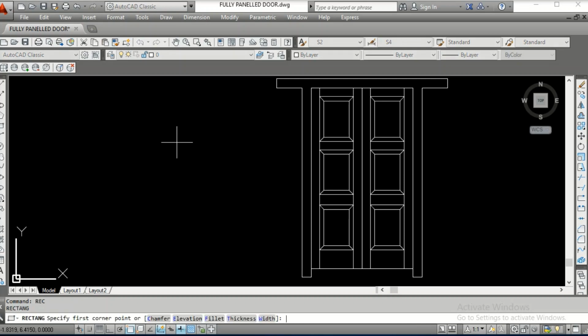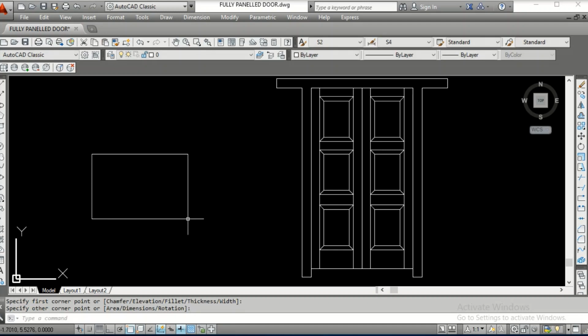Let us say there is a small rectangle here. How are you going to dimension this? So go for dim. Type the dim command. Click on either side. Type horizontal first, then horizontal. See, you got the text. Press enter. Similarly, vertical. VAR for vertical. Click on the 2 points, left click, and again press enter. See, you can do that with the mouse also. The right click stands for enter, it is equal to the enter button.